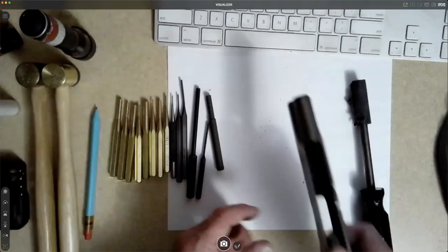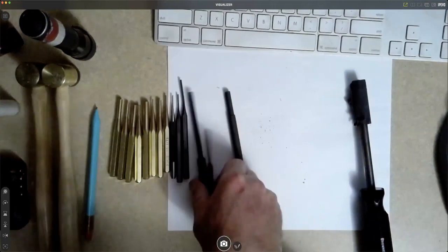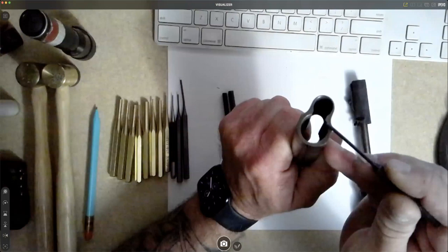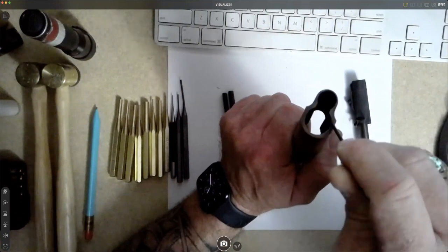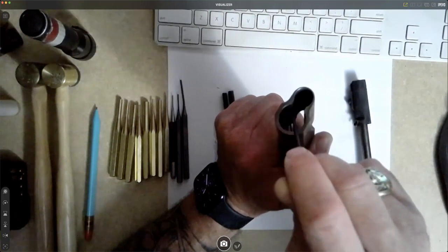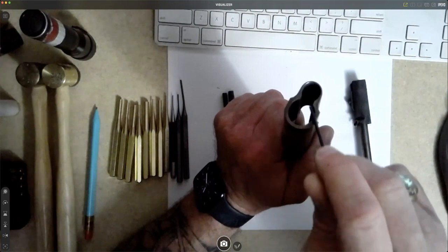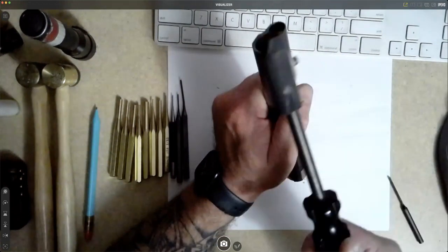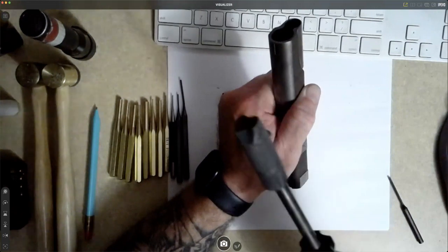The problem you run into with the Cratex is that you've got this sharp edge here and that sharp edge here. If I'm polishing around, I'm going to end up tearing off, I'm going to break that corner. So I'll polish that corner out. The other thing is it's going to bite into that Cratex, that impregnated rubber, and I'm just going to eat through that. So while it's slower, there's a reason why hand tools have a purpose, right?